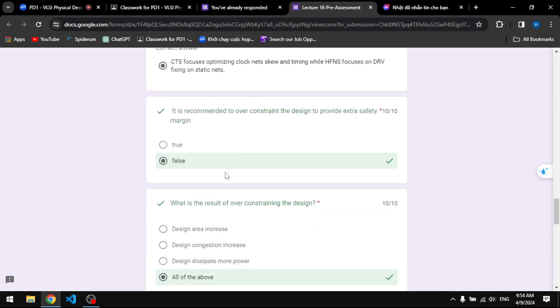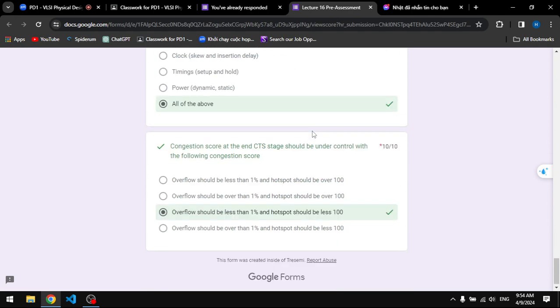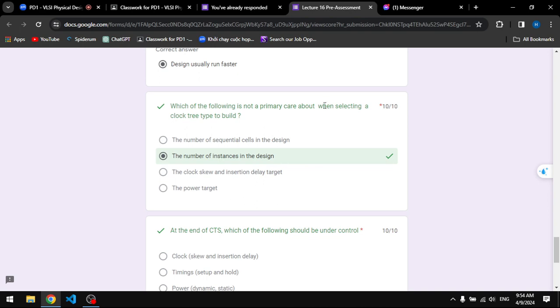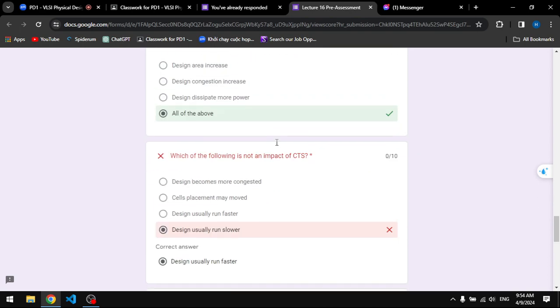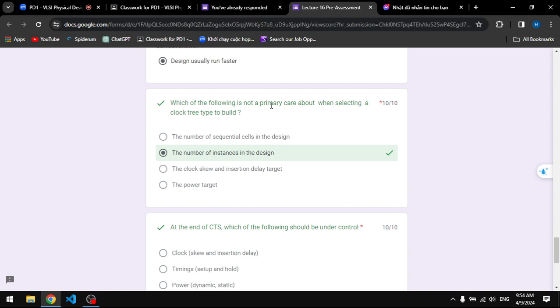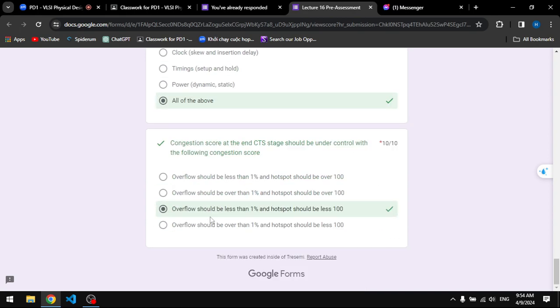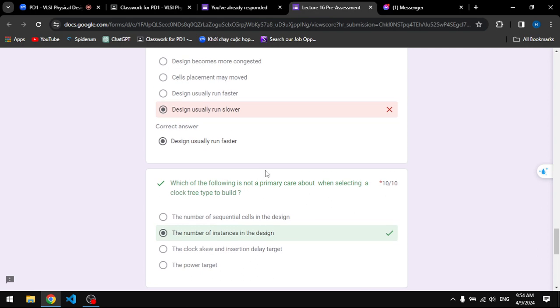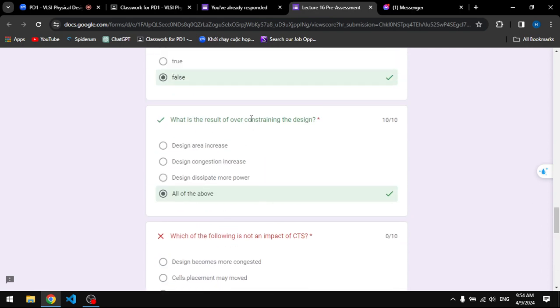The reason you insert a dummy is because you need to use it right away. You connect it to slow down the delay on the shortest path, the fastest path, to balance your clock tree, or to fix any other timing issue you have. You can manually do this on any signal you want, but the CTS tool will use this technique to balance the clock tree.